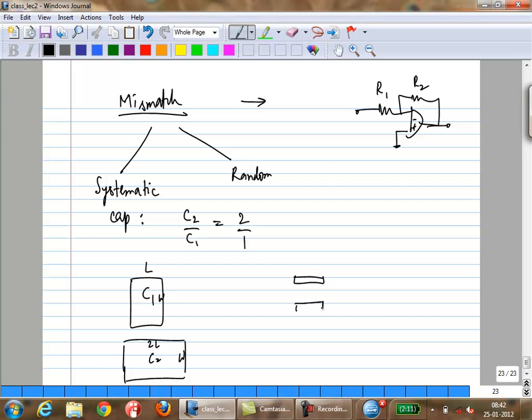In reality, ideally, let's say this is the side view of the capacitor. You want the field lines to go directly vertical, from one cap to the other, for a parallel plate. But in reality, you have these fringing field lines on the edges. Okay? Why? Because that is where you have a sudden change in boundary conditions for your capacitor, right?